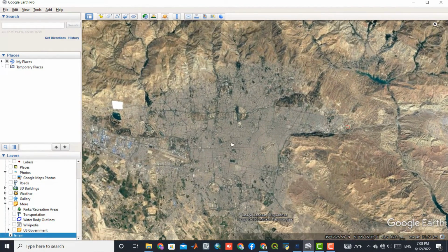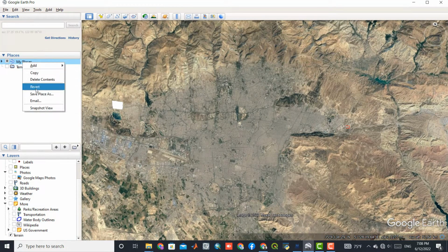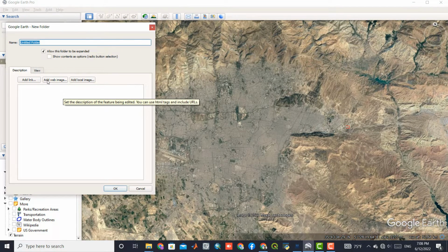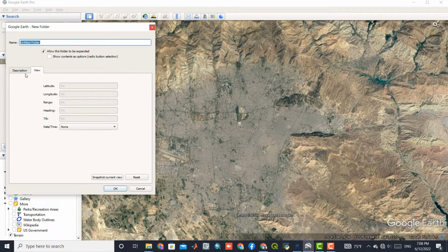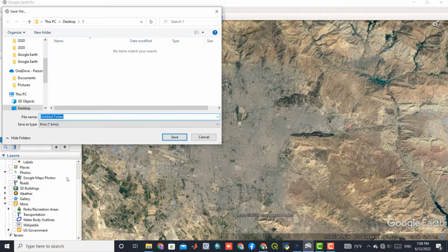If you need to collect points, lines and polygons from images in Google Earth, you need to create a folder. Creating a folder and saving all the layers created inside it makes it possible to save and import the folder only once when saving the layers and when necessary to open the saved layers inside ArcMap software, otherwise we have to save them one by one.